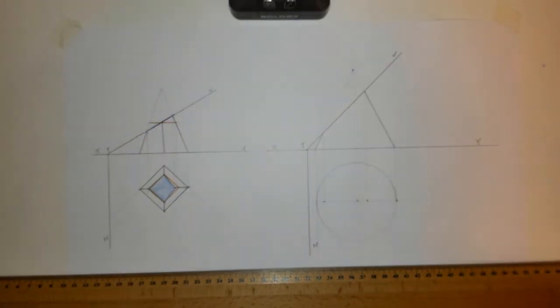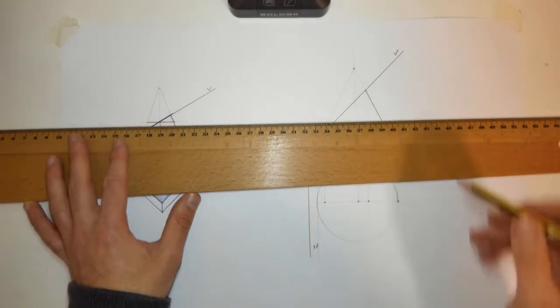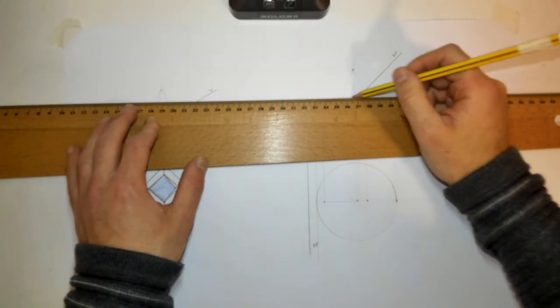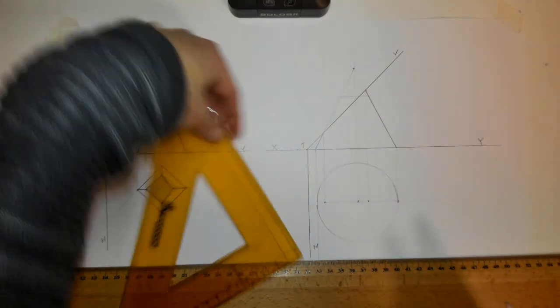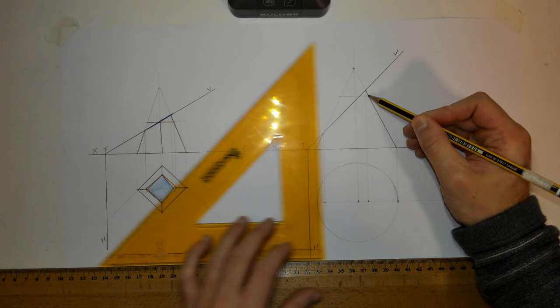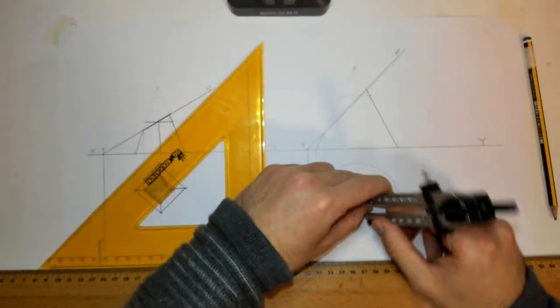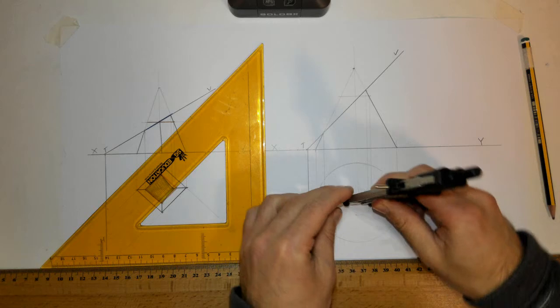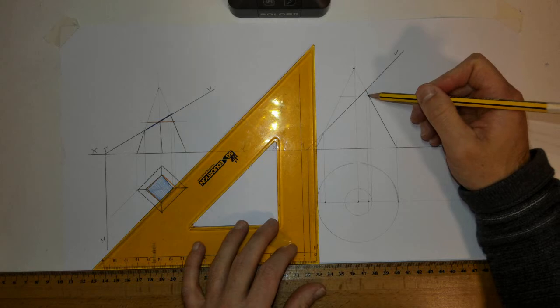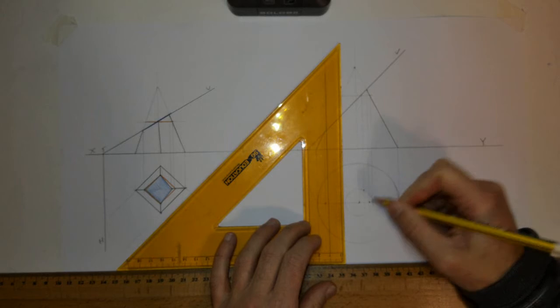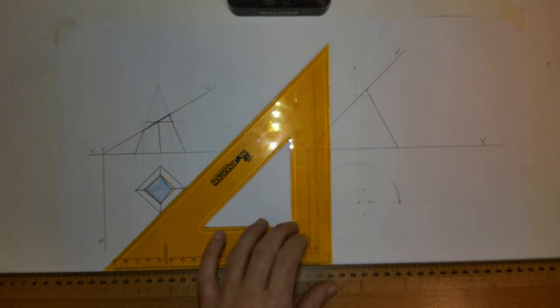After that, it's just about taking a number of horizontal cuts in between. The first one I can just take randomly is there. What I do then is, where it hits the extreme generator on the cone, take that down, and I'm going to draw the plan view of that cut. So it appears as a circle. And where the horizontal cut hits the cut there, gives me this point and this point here.